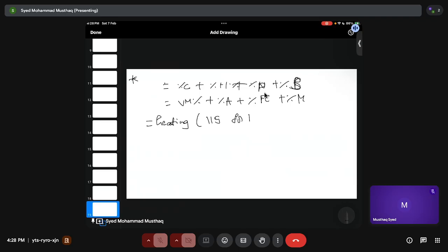This is the standard process to remove the moisture. And if you want to remove the volatile matter, you heat up to 925 to 950 degrees centigrade for 10 to 20 minutes. Then the volatile matter comes out. Then you measure the weight, and you know how much has been lost.